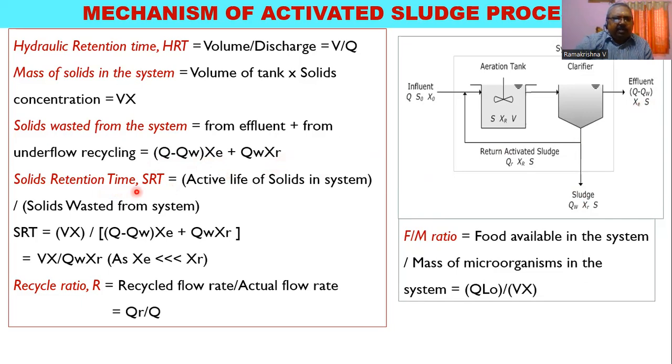Solids retention time, SRT, is the most important. HRT is nothing but only volumetric flow: how much water is retained, only one flow-through cycle. But here the active life of the biological solids is more than the retention time we normally have for the aeration tank and clarifier. That's why solids retention time is more important.